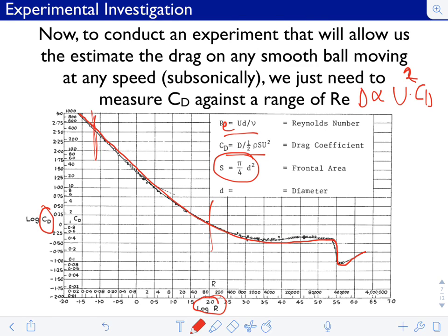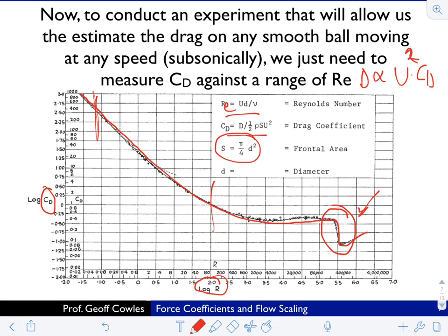There are places shown here in this phenomenon where you actually have an increase in Reynolds number, which could be coming from an increase in flow speed, and you have what is actually a drag decrease, for a very short reason. This is related to a transition from laminar to turbulent. And spherical objects like this benefit from turbulent flow, which is one of the reasons that golf balls are dimpled, in order to push them into that turbulent world to drop their drag. And we'll discuss that more when we get to viscous flows.